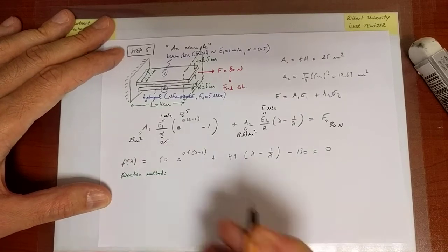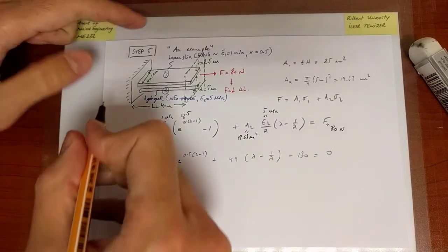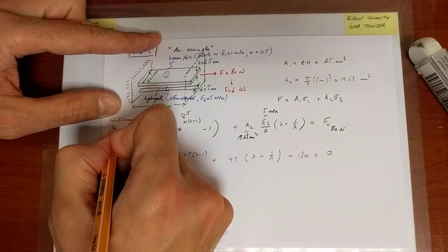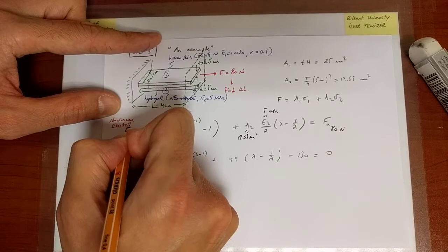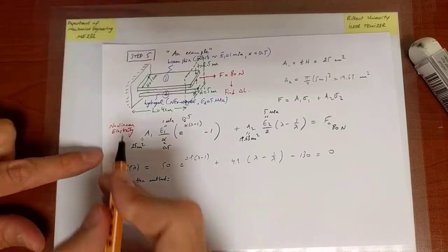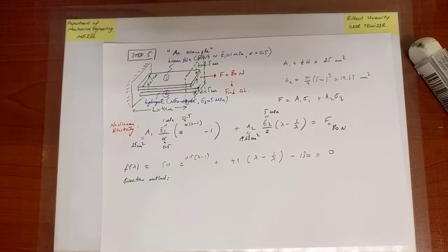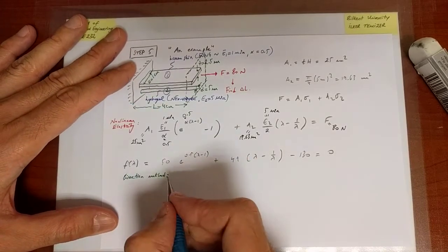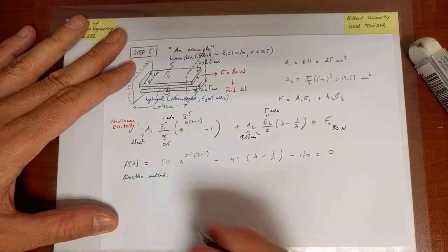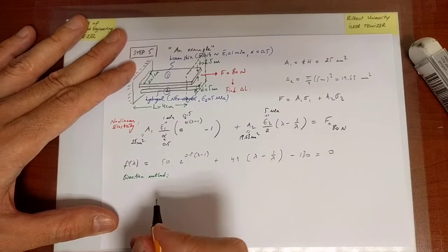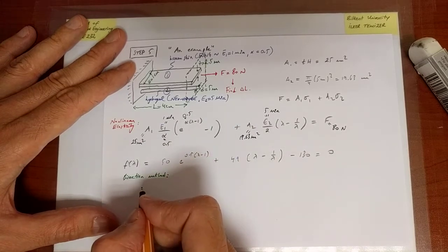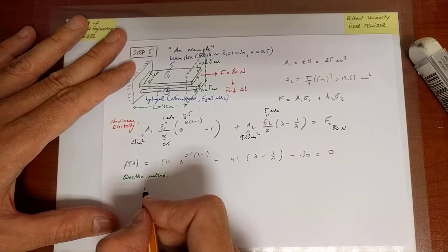method. And here, notice we are using, again, let's highlight, it's a problem that's for nonlinear elasticity. I'll shortly make a comment on the type of accuracy or prediction you have when you neglect the fact that you are dealing with nonlinear elasticity here. So the bisection method starts off by, first of all, noticing that the force is positive, so I'm pulling, I expect a positive, of course, strain, therefore stretch is larger than 1.